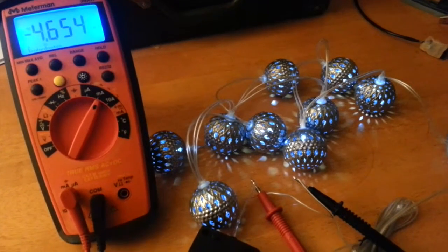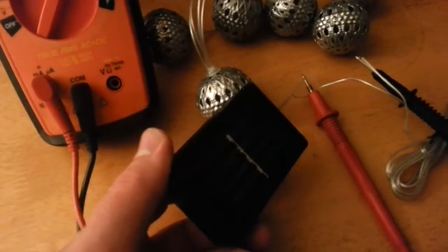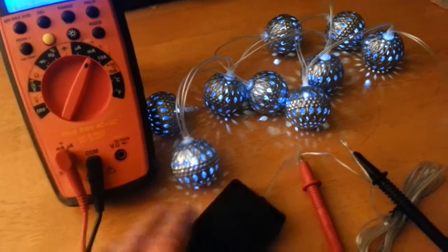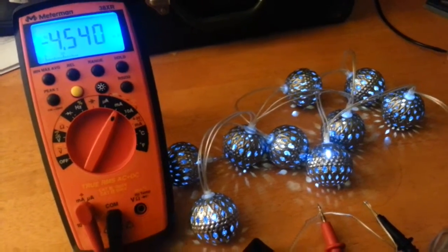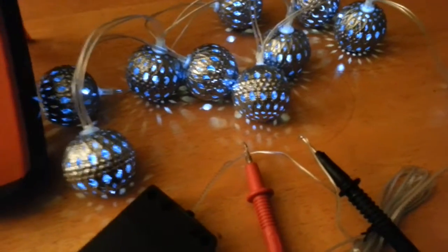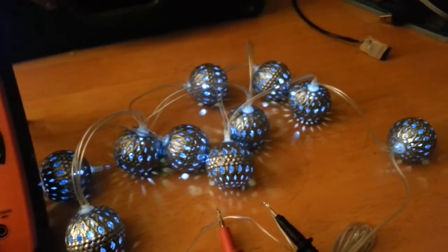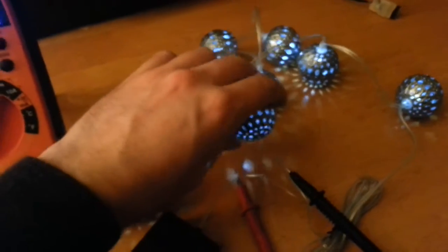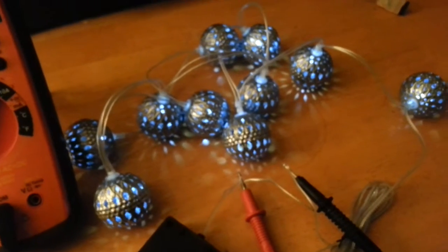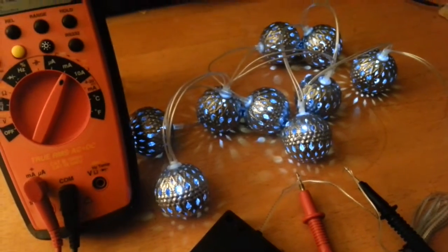I thought it'd be interesting to take a look at how much current these things draw when powered from their little solar control circuitry and the single nickel metal hydride cell that will inevitably be within this box. I'm always struck by how little current these things seem to take. Here we're measuring about 4.5 milliamps using a multimeter inserted in series to measure the current. So it's only about 450 microamps per LED, and yet they're still glowing quite brightly and pleasantly and casting nice patterns on the table. While you might typically think to run an LED at 10 or 20 milliamps, these guys are running quite adequately on microamps.